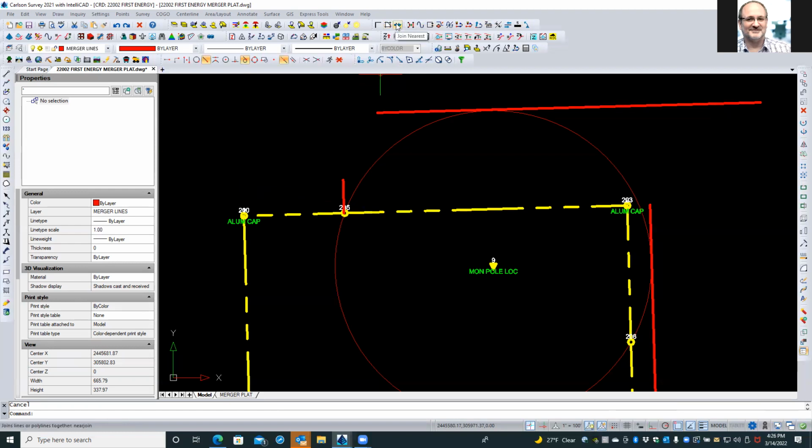One more to the left, right there. Click, and click near one of the ends of the line you just drew. Now that little pointer shows where it's going to adjust. Now down below, you have all those options at the command line. You want to type T for total and then 20. Okay, hit enter to finish.